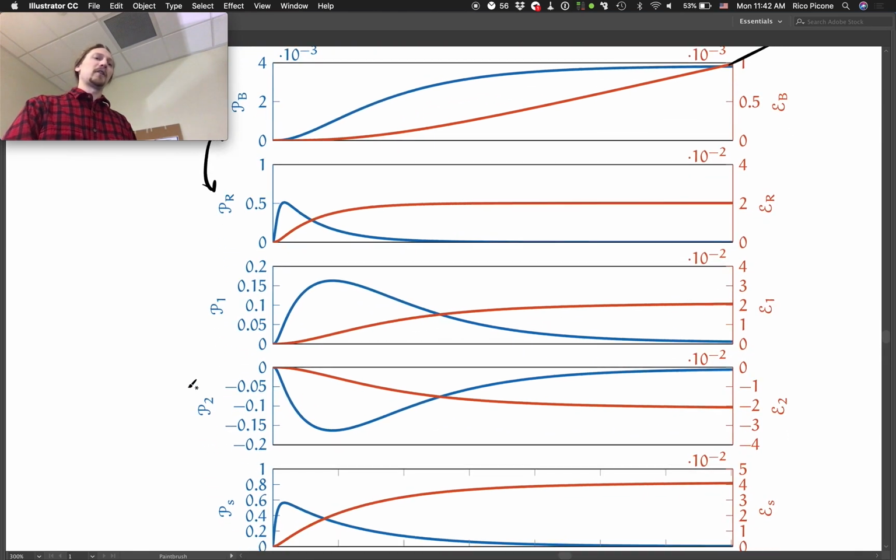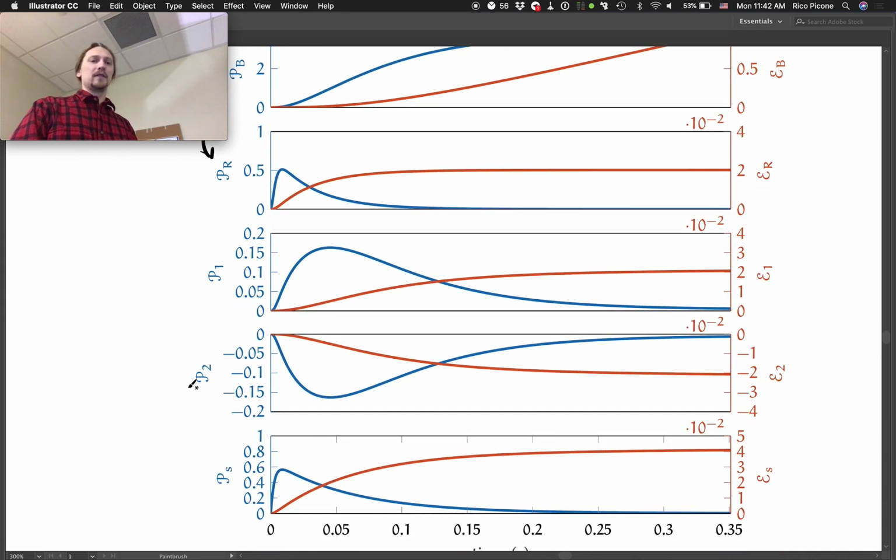The heat that gets generated in your motor is detrimental, and it also consumes a lot of your power. So efficiency-wise and heat-wise, usually it's your windings that are the biggest problem. So cooling your motor to get rid of the heat is important if you're going to be running it at high torque, high power on the electrical side. But it still doesn't help you efficiency-wise. Efficiency-wise, it still sucks because you're dissipating a bunch of energy.